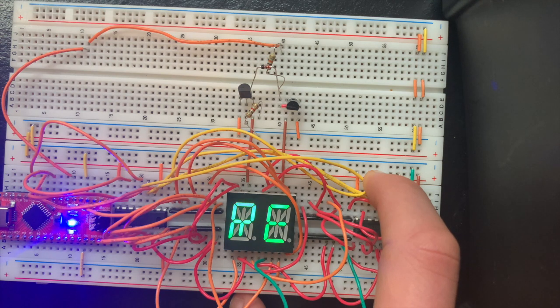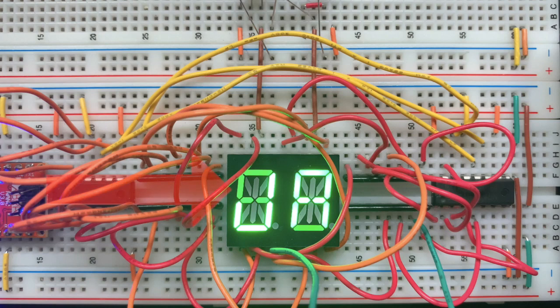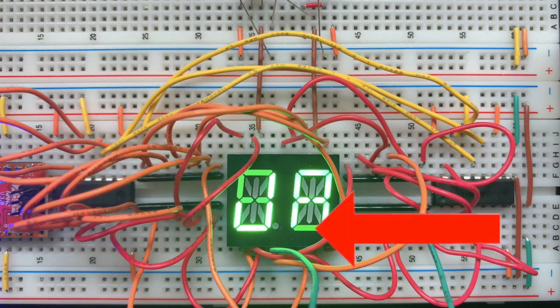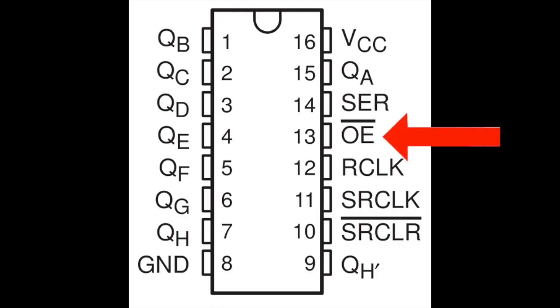that being ghosting. Ghosting occurs when there is a slight error, and while not as visible, the opposite character will be slightly displayed on the wrong display. This can be fixed, though, with a simple change, by wiring the output-enabled pins of the 595 IC chips to the Arduino, and wiring them low before shifting out, and high directly after.